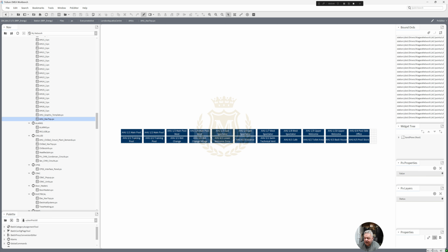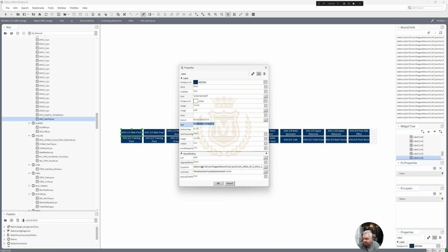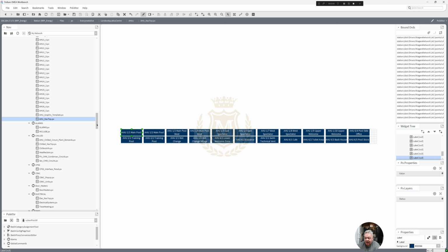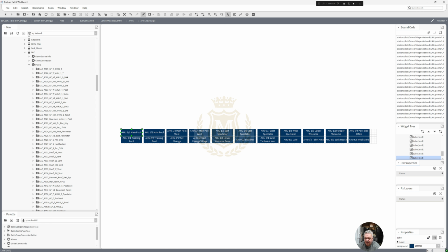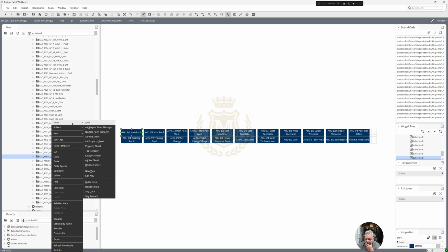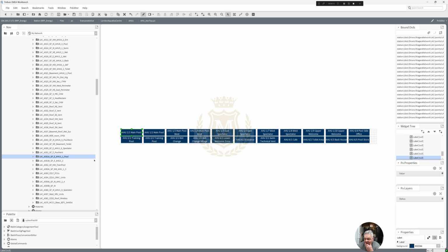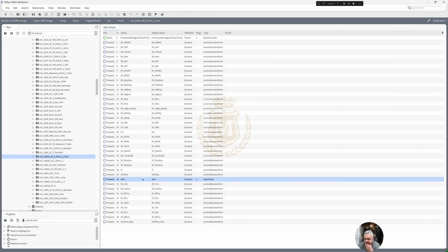When you click on that, you go to the Niagara network, LAC, short for the site, points, and then you go to the BACnet points for that, which I attached. And how I attached it, if I take out AHU11, where are we? There we go, AHU11. Let me go views, let me go AX slot sheet, and remove that. So I'm going to delete that slot from there now.